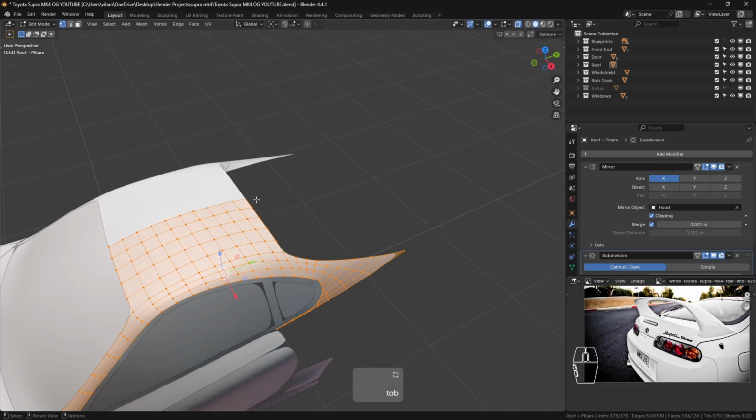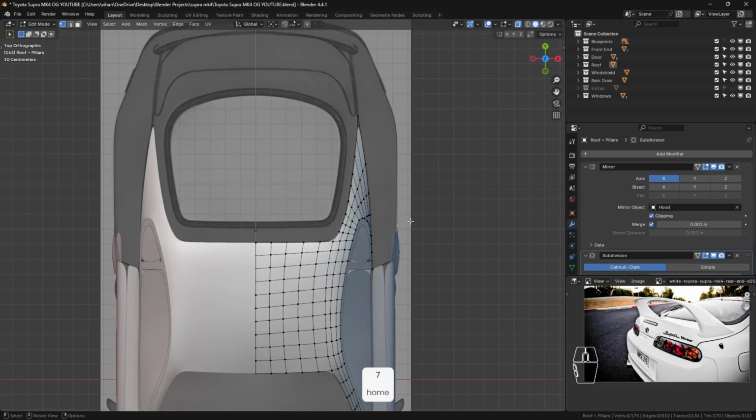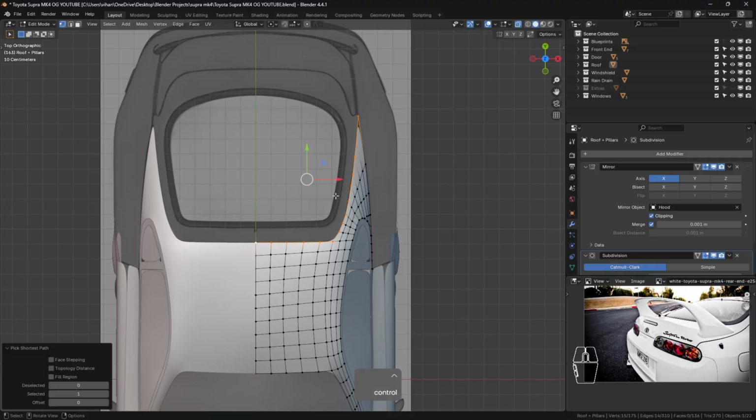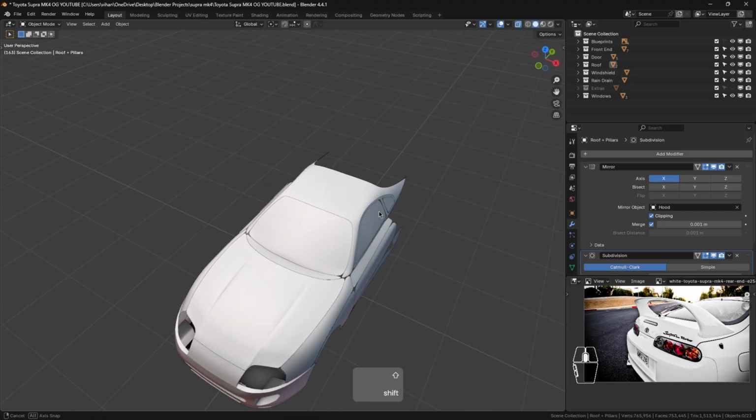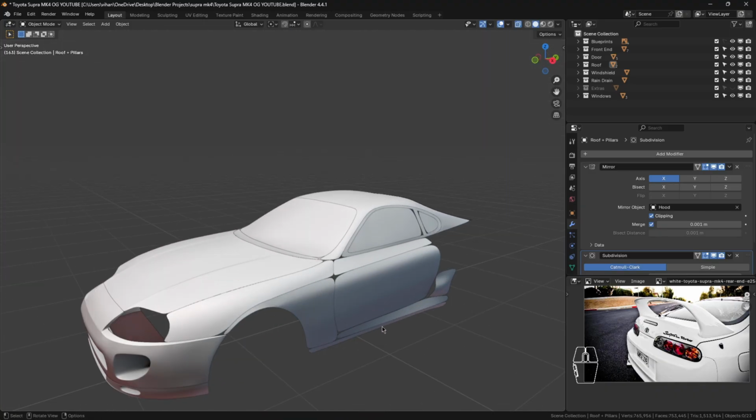So first of all, let's do one thing. Go to 7, that is the top view, and just select this entire edge line right here. We need that perfectly aligned. Just duplicate it and separate it, alright? Let's rename this Door-Sill first. Door and sill. And just make sure that's in the door collection, alright?